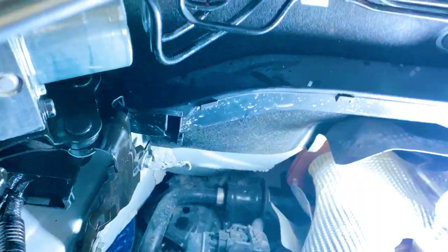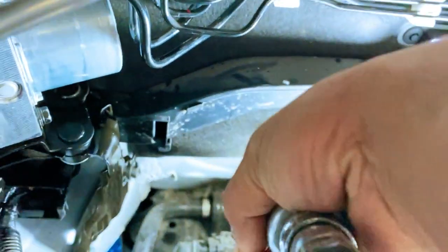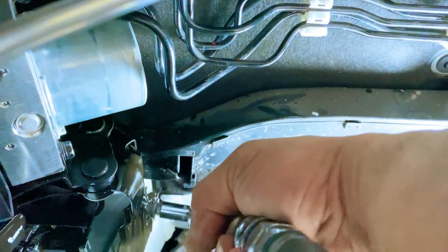7 o'clock, brake actuator removal. Now let's move on to the physical repair. Before removing the brake actuator, make sure the vehicle is safely supported and the brake system is protected from contamination. The repair procedure begins with draining or removing the brake fluid as required. Be extremely careful with brake fluid. If brake fluid gets onto a painted surface, wash it off immediately.